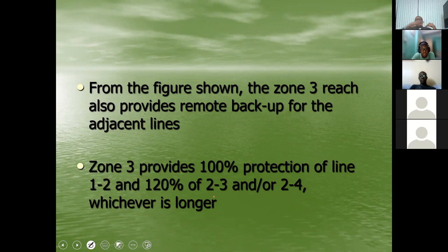So you're going as far out as possible on this zone 3, which means that the delay on this is going to be even longer, because by putting in the zone 3 time, you're giving the impedance relay on 2 lines down the road the chance to operate, if that is indeed where the fault is.